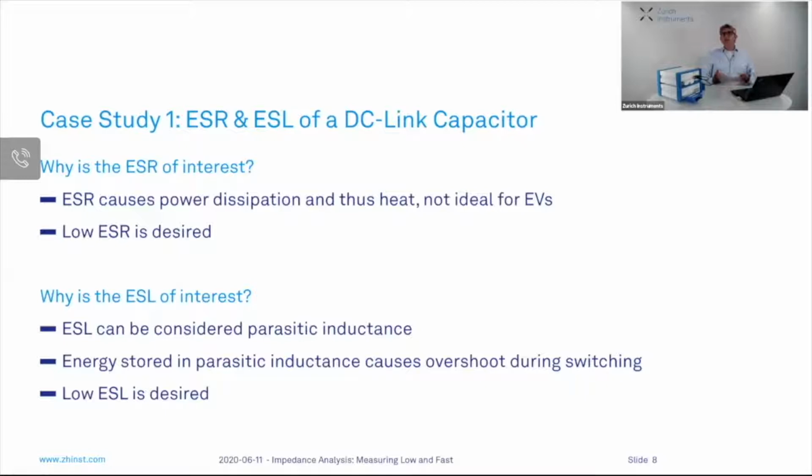It's very important that these components have both a low ESR and a low ESL. State-of-the-art components have been developed with ESR below 1 milliohm and ESL on the nanohenry level, such as the component we're measuring today. But let's start with ESR.